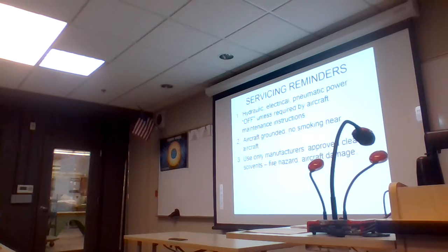Use only manufacturer's approved cleaning solvents, for reasons of fire hazard or aircraft damage. There are a lot of coatings used on components that are damaged by commercial cleaners of unknown nature. The manufacturer will specify what's to be used when and where, and don't make substitutions. You can easily damage components. You might even void a manufacturer's warranty by using the wrong kind of cleaning material. On an H-60 aircraft with the elastomeric rotor head, if you put a little bit of WD-40 on that elastomeric bearing, the same thing is true with a lot of the other rubber components. They're not tolerant of it.